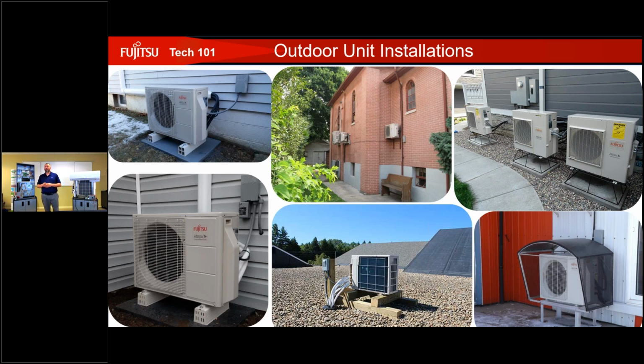Roof type installations. We spoke about the new louvers, the new wind baffles that Fujitsu has released. This would be the perfect application for that. We want to make sure that we don't have the wind blowing across that outdoor fan.